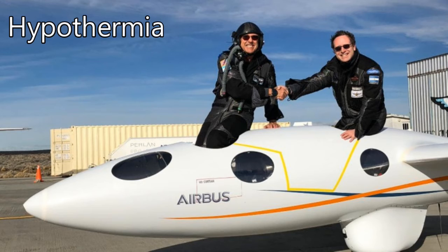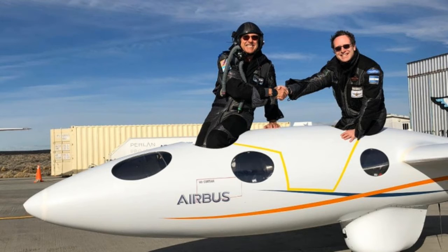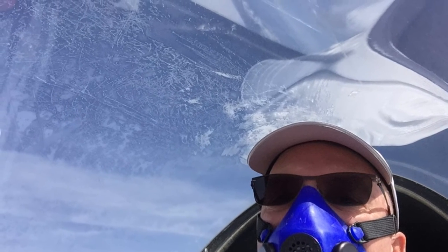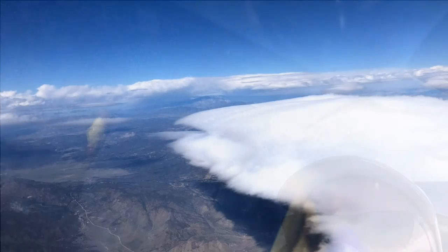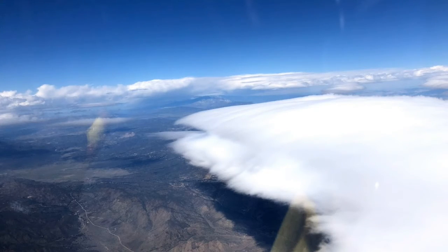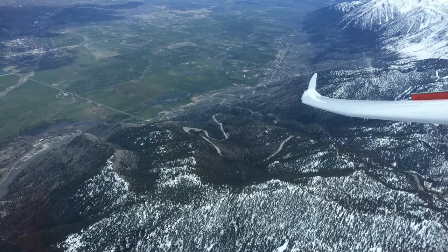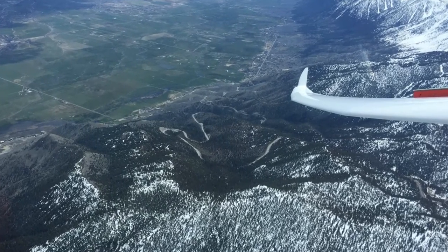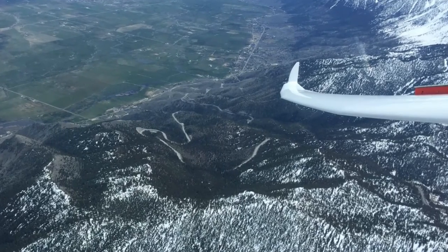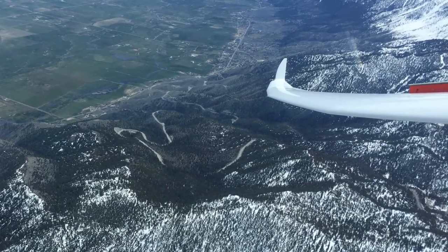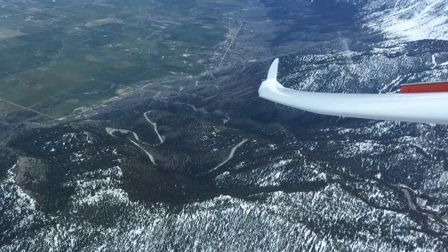It might be 90 degrees on the ground, but shorts and well-ventilated sneakers are not adequate clothing for high-altitude flights. It can be well below freezing at these altitudes, leading to hypothermia and frost forming on the canopies. These same cold temperatures can be hard on glider gel coat finishes if they are warmed back up too quickly. Additionally, freezing of any water that had accumulated in places like the spoiler box may lead to the necessity of a no-spoiler approach.